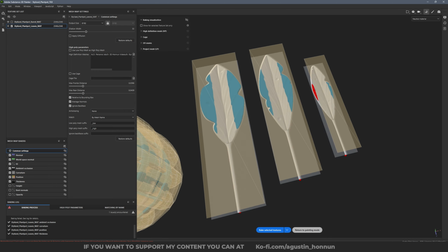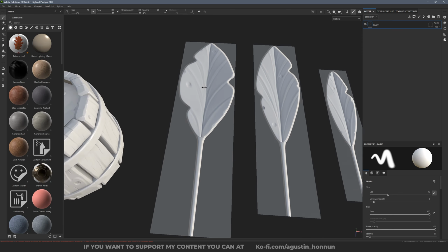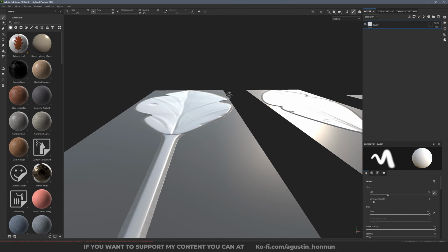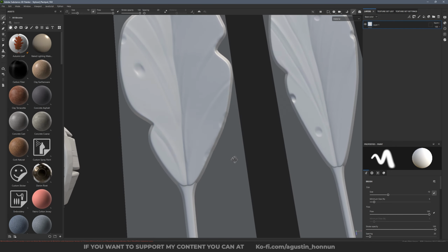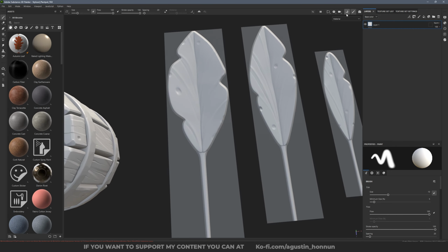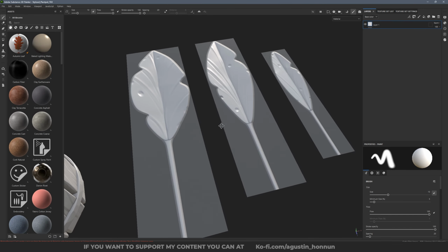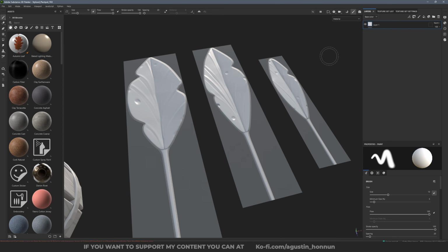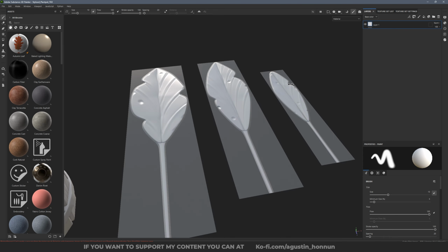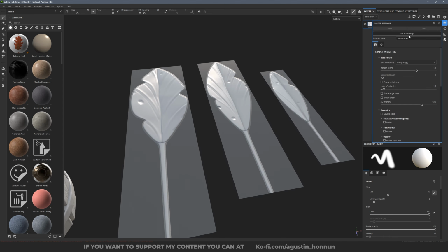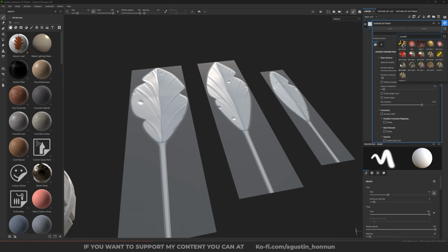Okay, perfect. We bake this, as you can see, but we need an opacity mask information here. So now we need to bake the opacity. That simple opacity layer will help us to add opacity information here in the lips. So I'm going to change the shader here to blend PBR alpha blending.